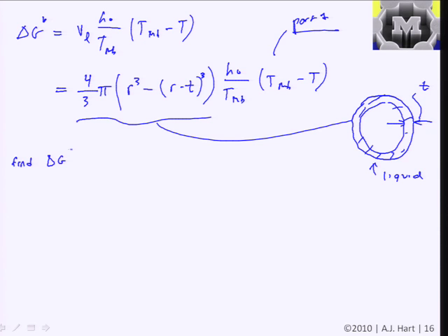So now we want to find the change in free energy due to the surface. So if we imagine going from the case of a solid to the case of a liquid and a solid, then in the context of surface energy, like we were talking before, we start out and we have a surface with energy gamma_S, and we end up and we have a surface with energy gamma_L, and we have a surface with energy gamma_SL.